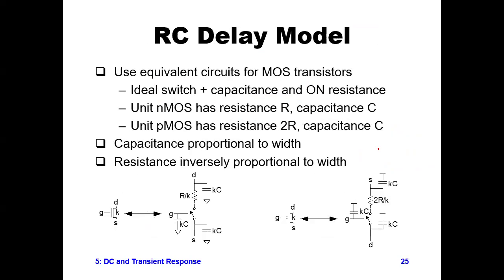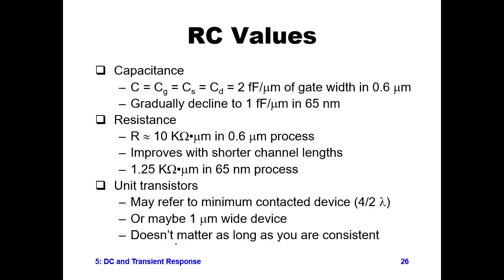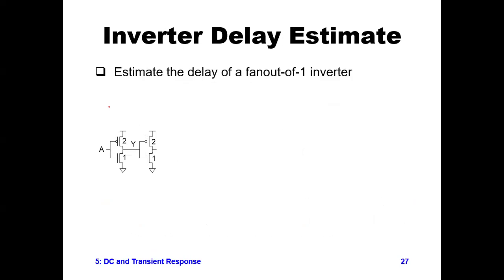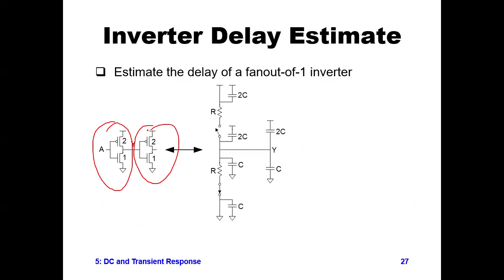Probably this PPT has it. I'll show you. Yes, this way. This is your MOSFET, shown as a resistance and a capacitance. I will explain how this RC delay model is created with NMOS only, and then with NMOS and PMOS. You see, this is the model for NMOS, and this is the model for PMOS. Using this NMOS and PMOS, we can create a similar model for the inverter. This is your fan-out of one: one inverter is driving the other inverter. Don't worry, I'll show you all these theoretical concepts in your next lecture on Monday.